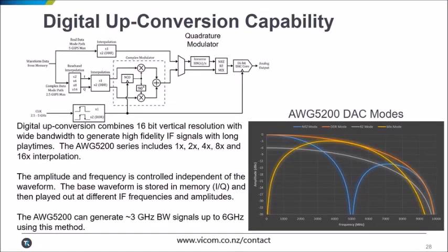Reducing the size and cost for these radar and military systems is driving the evolution of modern DACs to integrate more functionalities into a single ASIC. Some of the more advanced high-speed DACs also incorporate digital signal processing and conditioning functionalities such as digital interpolation, complex modulation, and numerically controlled oscillators, or NCOs. This enables direct generation of complex RF signals in an efficient and compact way.